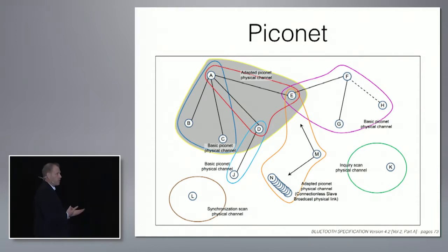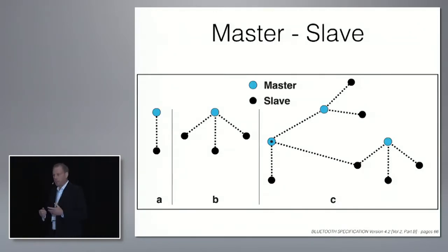Bluetooth devices themselves operate in what's called a Piconet, or a personal area network, which is designed for short-range communication. When looking at the specification, that range is typically about 10 meters or 30 feet, where devices communicate with each other. Devices communicate in what's called a master-slave association. Within an individual Piconet, you can only have one master. That master is responsible for slaves connecting to it, getting onto the Piconet, and synchronizing the Piconet. That's really a lot different from what we're used to with Wi-Fi.